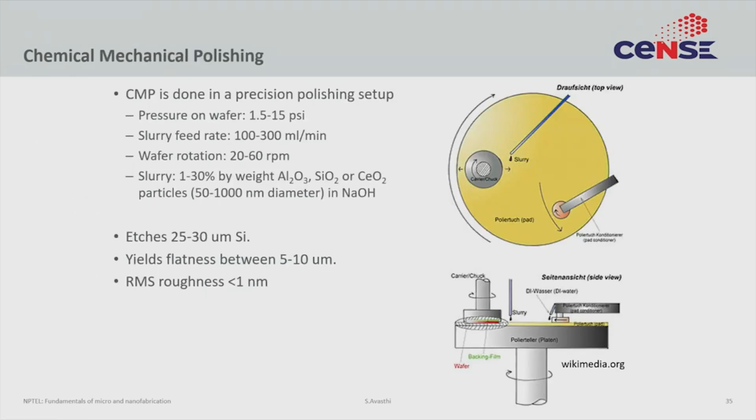After this is done, you still have a relatively rough surface. So in order to smooth it to an optical finish, you then do polishing. This is very similar equipment to what is used in lens making or in optical component making, where they also get a smooth surface through polishing. So this is a typical polishing system. You take your wafer, you put some weight on top, and that silicon wafer is rotated on a bed.